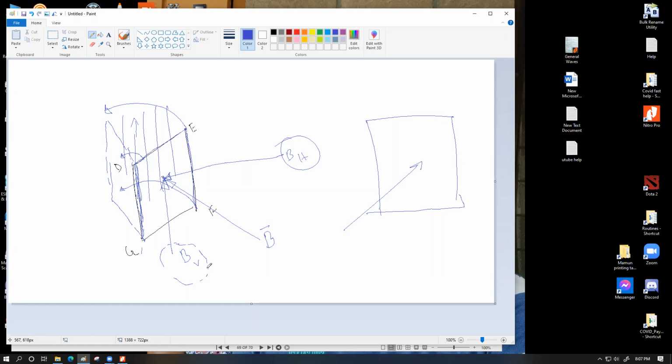It was a vertical component element. Now comes the horizontal component element. So this is the horizontal component. For the initial position, the horizontal component is perpendicular to the face of this thing. So currently you have the flux linkage across this coil for this orientation, phi due to the horizontal component, equal to B of horizontal component times A times sine 90, that is 1.